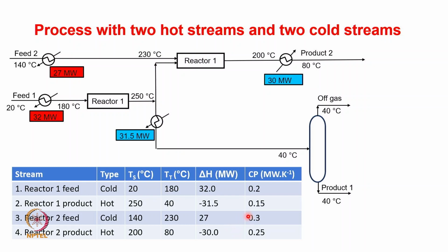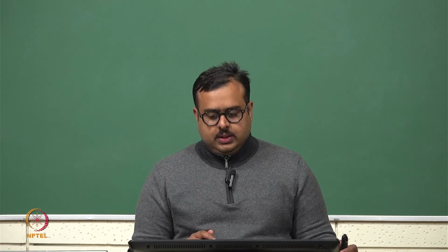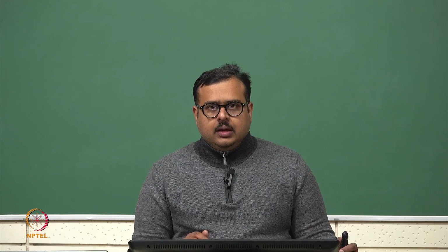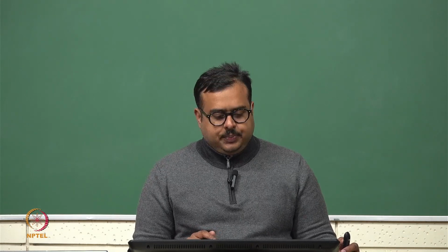So now we have multiple aims in this part of the exercise. Try to draw the composite curves. Identify what is known as the pinch point. If you identify the pinch point, can we use the concept of pinch point to redesign the network so that maximum heat recovery can be obtained, and how to do that systematically. That's what we are going to do in the remaining part of the lecture.